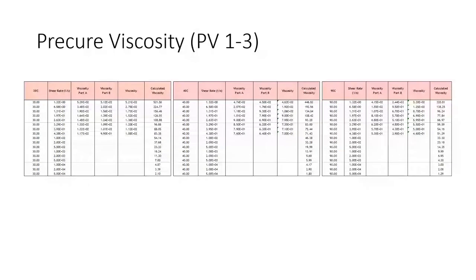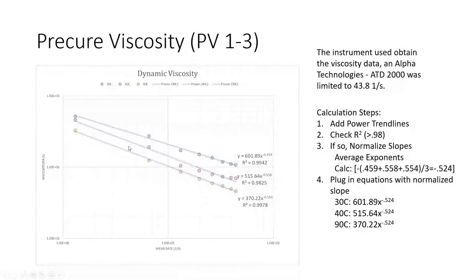I'm going to go all the way back here. You can see the slopes of these lines are not perfect, and you can see that, of course, in the numbers as well. We have a 0.45, minus 0.459, and looks like 0.558. And that's because the data is not perfect. There is error in the equipment. There is error probably due to the sample. In many cases, we've run this test more than once and we've averaged the plots, and that actually helps. Run the test 3 times and you get a correlation factor that's usually 4 nines. So you can improve this. But we do see some slope variances.